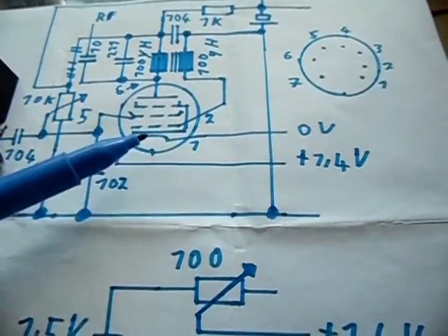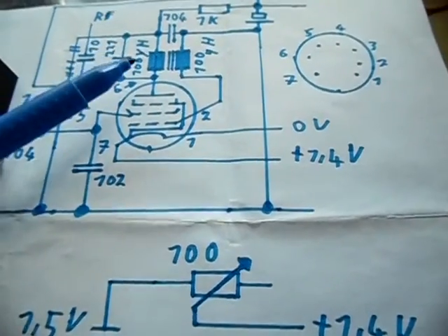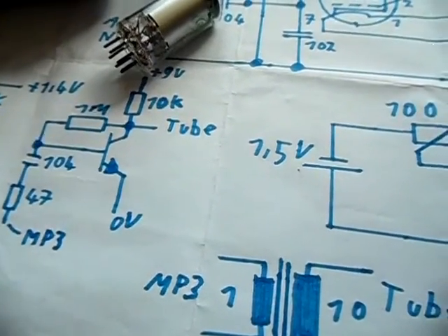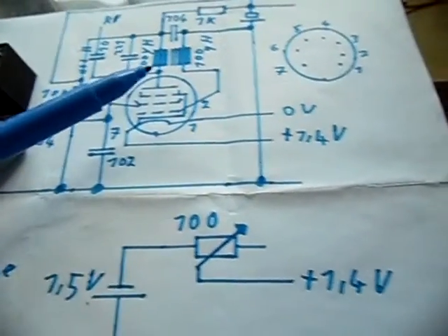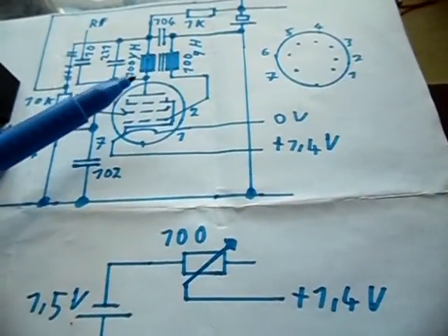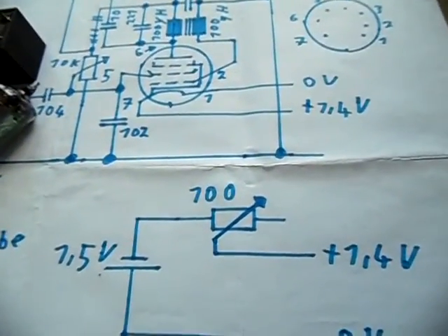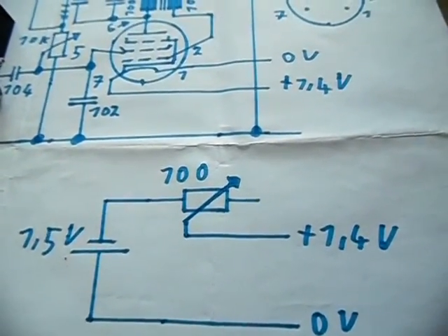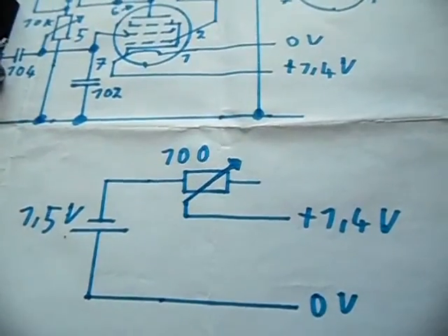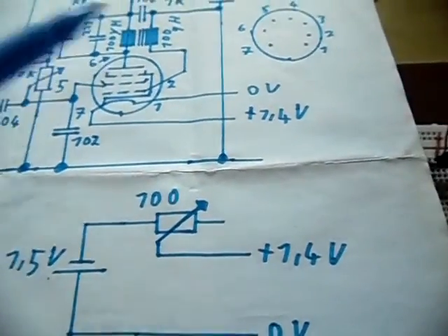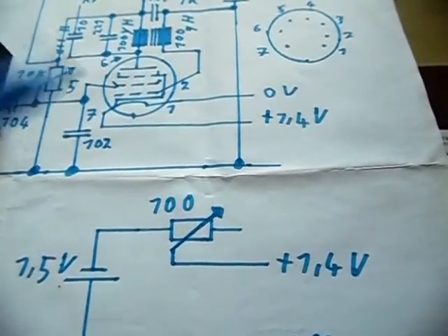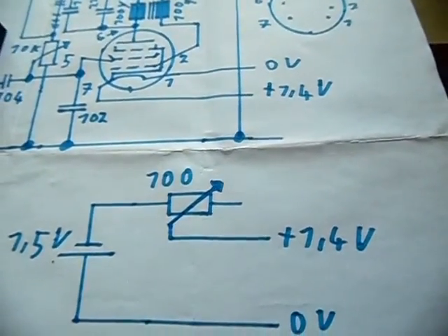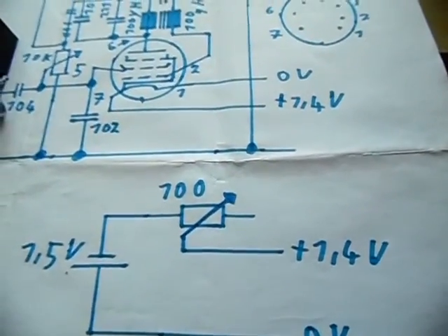Anyway, so tubes have three grids, and for example there's cathode, anode and a grid. The cathode would be like the emitter, the anode would be like the collector, and grid would be base. But if you just go ahead and connect cathode to ground, and for example an LED between anode and plus, and then you feed a signal into the grid, well, nothing happens. Even if you turn it on, it can be that the LED is lit up a little bit or is not lit up. That's because of these grids. And if you don't know how to connect a tube, you will definitely get in serious trouble with these grids, trust me. I made many experiments, and it makes you angry.